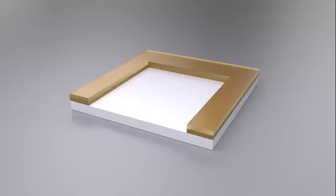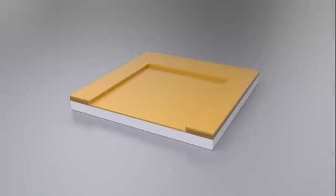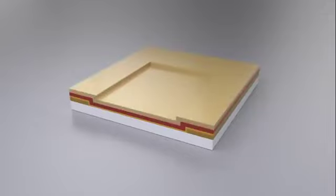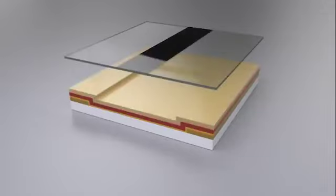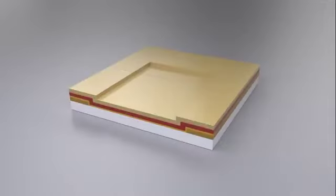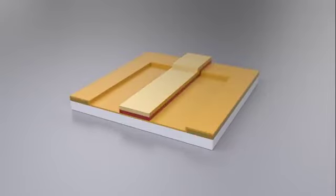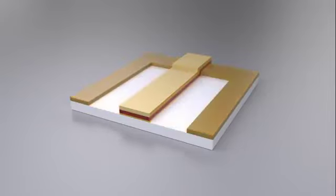Once the photoresist residue has been stripped and the wafer has been cleaned, the wafer undergoes further oxidation. Electrically conductive polysilicon is deposited on this insulation layer. Then photoresist is applied again, and the wafer is exposed to light through the mask. The exposed photoresist is stripped again. Now the polysilicon and the thin oxide layer are etched off. These two layers only remain intact in the center under the photoresist.